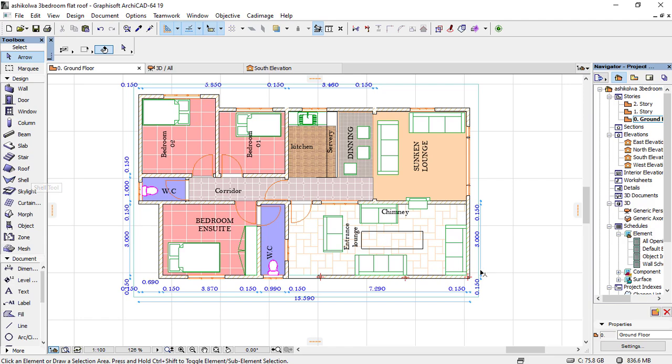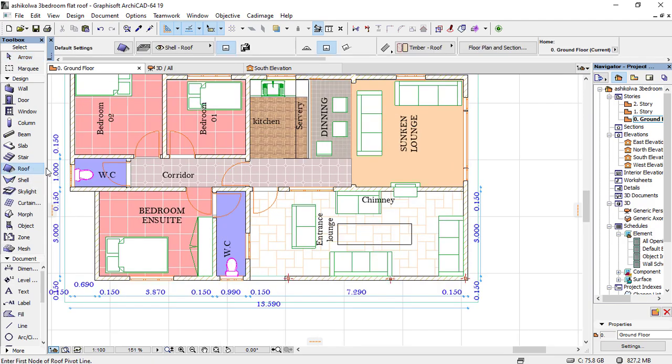So the first thing you do is you go to the roof and then you select roof geometric method single plane, and then you select construction method rectangular. So the front part is up to this point, and therefore you just need to draw the line work. Immediately you select the rectangular method, select the line work, and then you draw the line work up to the end.